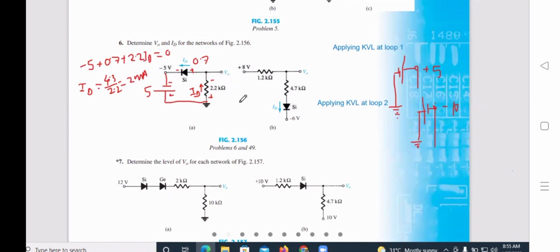What is VO? You can see VO top side minus, bottom side plus. So it is opposite of our conventional sign taken. We normally take top side plus, bottom side minus. So VO polarity will be negative because now here output is top side minus, bottom side plus.